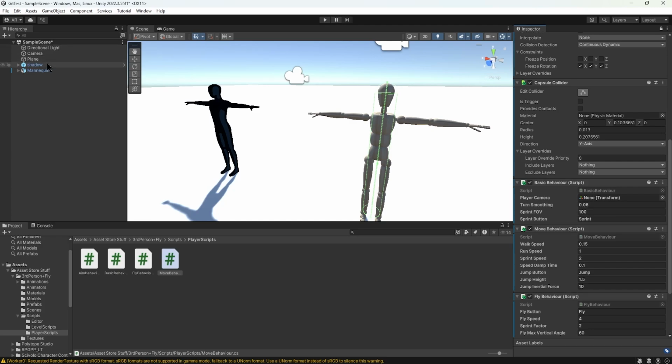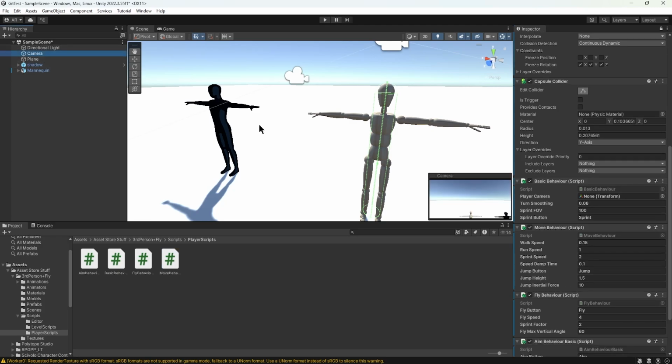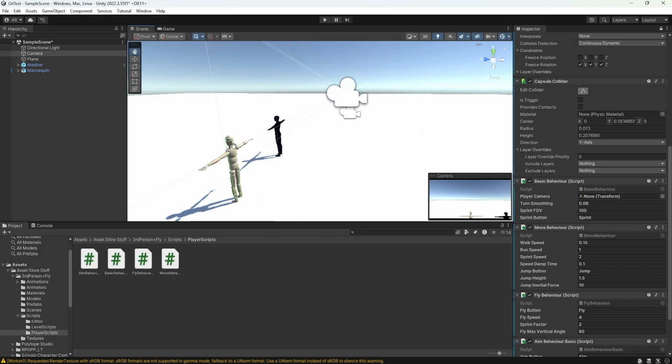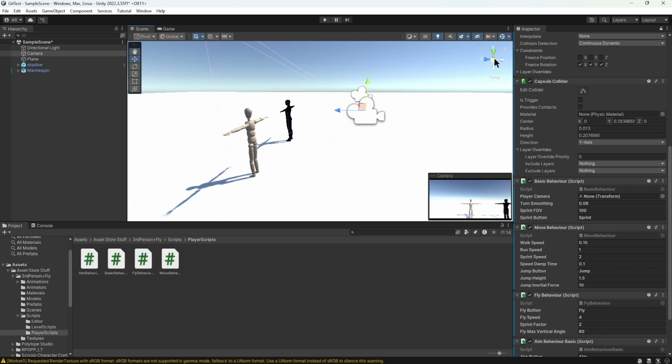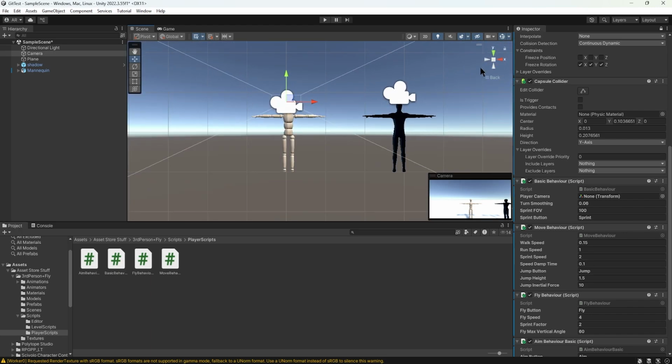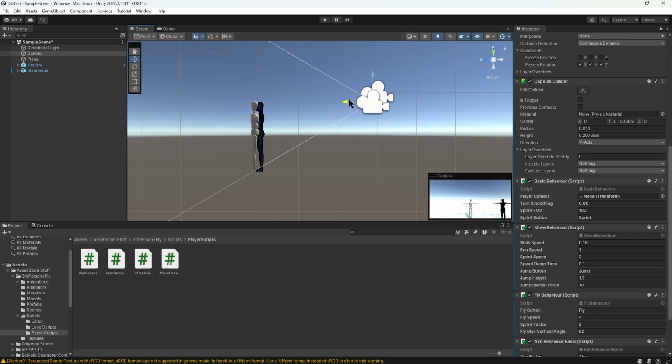Now we need to attach the camera. So speaking of the camera, let's go ahead and get the camera set up here. Let's bring it down a little bit. Let's actually do orthographic view so I can get more fine control over the positioning of this camera. It doesn't need to be exactly where Shadow's camera is.